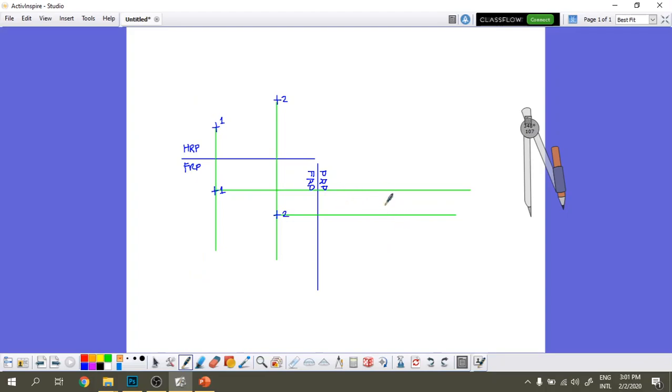So one view away will be this one, so that's why we did projection lines here. So this is a projection line. Point 1 projected along this line, which is perpendicular to this line. Then for distances we do two views away. So if this is PRP, this is one view, two views. So we copy this distance, copy this one, then project it.